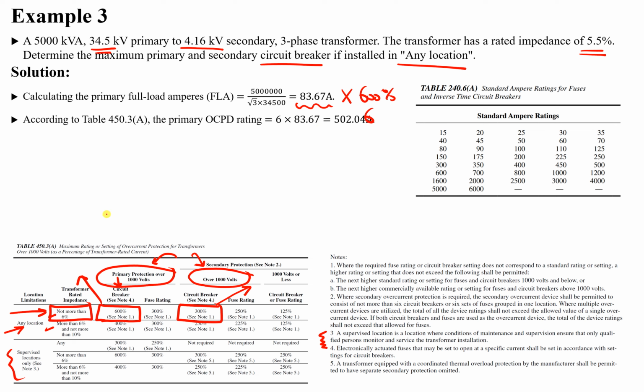Great. Now the question is, which one should I use? Before I say this, we have to make sure of one important part. This table here is for less than 1000. Now, greater than 1000, less than or equal to 1000. For greater than 1000, we should look for the commercially available ratings. The commercial availability may not be this great, so above 1000 has its own circuit breakers and fuses which are not found inside the NEC standard. You can find them commercially.